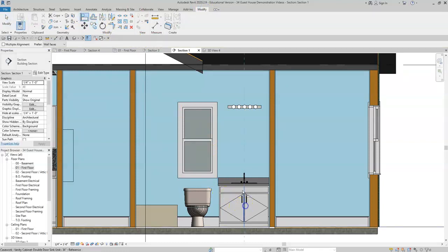So we're going to make it center up and probably let it be about the same height as the window, the 7 feet. If we get a mirror here and you want to lower it, that's okay. You wouldn't want it too low because it would blind you by the light. But other than that, that's how you place a light on a wall. And this will be the same for the exterior.